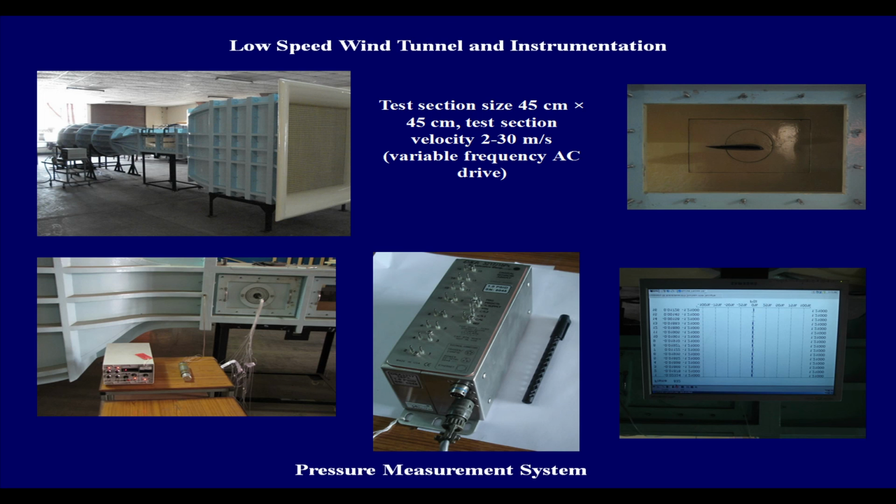You must have set it in the beginning of the experiment and ensured that when it was just sensing the ambient pressure, it was showing you a 0 reading, right? And then when some other pressure comes in, it gets deformed to some extent additionally, generating a certain change in the output voltage from the Wheatstone bridge circuit, and that signal is going to be shown in the readout unit here.